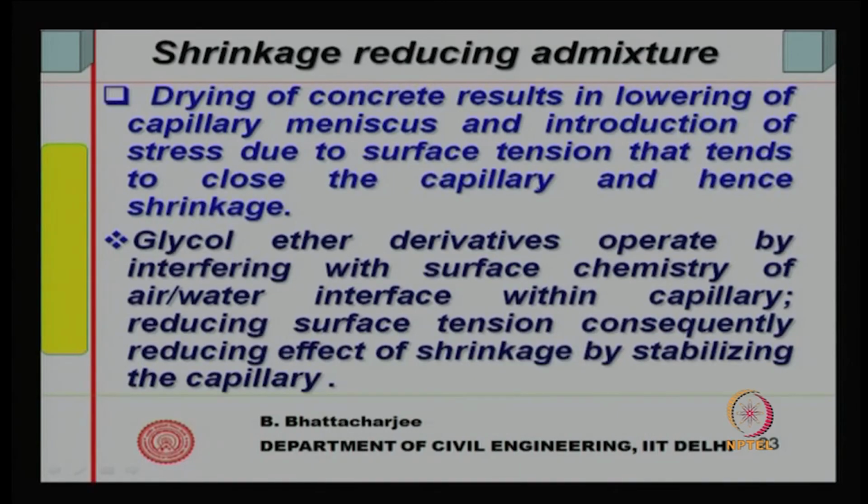Then there are shrinkage reducing admixtures. You see, drying of concrete results in lowering of the capillary meniscus, and since the capillary meniscus will lower, stress is introduced due to surface tension forces.